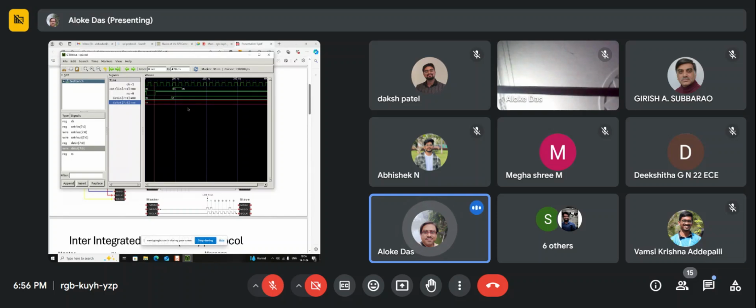verification of your design. So these are the three things basically you have to do. You have to create your own design, keep it in a .v file, then write your test bench and instantiate your design inside the test bench. If you have a master slave configuration, do it, and then write the test bench very thoroughly.